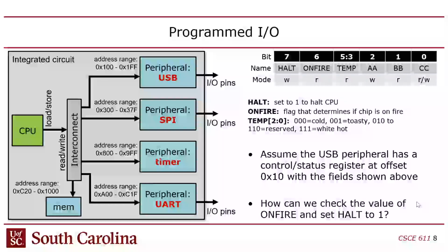Instructions are 32-bit values for a 32-bit processor, and then they have different fields. It's the same thing here. So whenever you interact with these, you have to spend a significant number of instructions extracting bit fields out of these registers to read them, or putting data inside these bit fields, right?